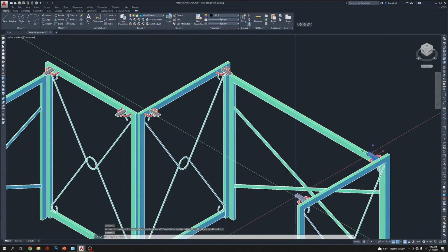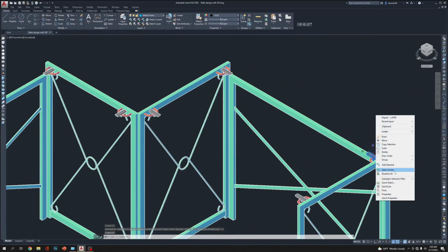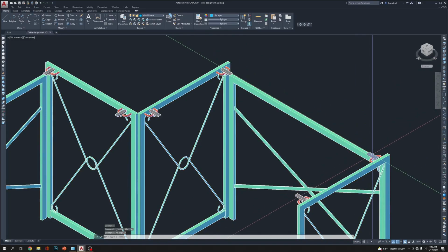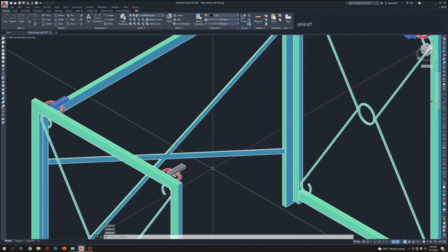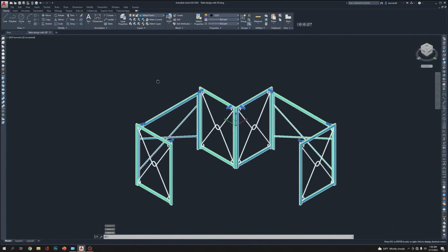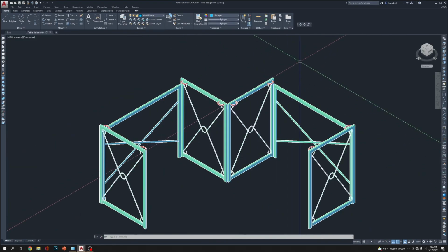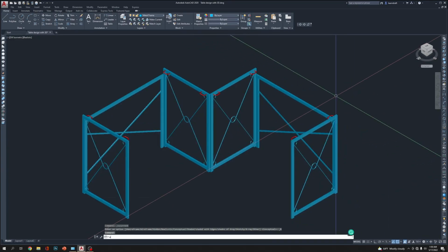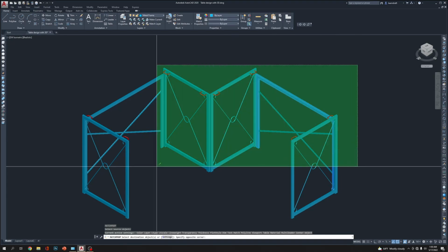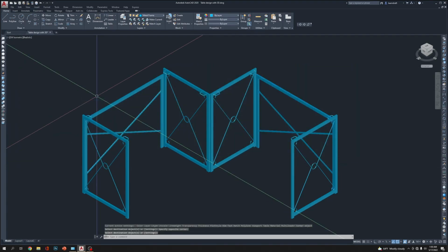So I'm going to select these, right click, select similar, selecting all the plastics, okay, 4 of them. Go to the metal frame, go with the wood, because it's going to be with wood, and the red thing is going to be with metal. So if I go to this 3D match properties, MA, enter, select this match properties, everything is the same color.